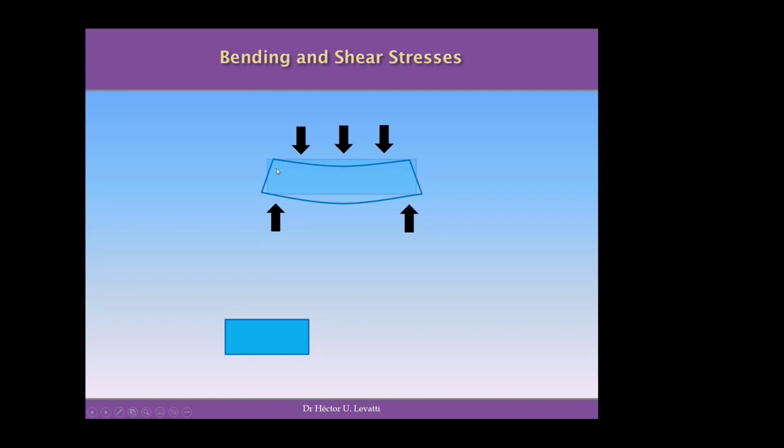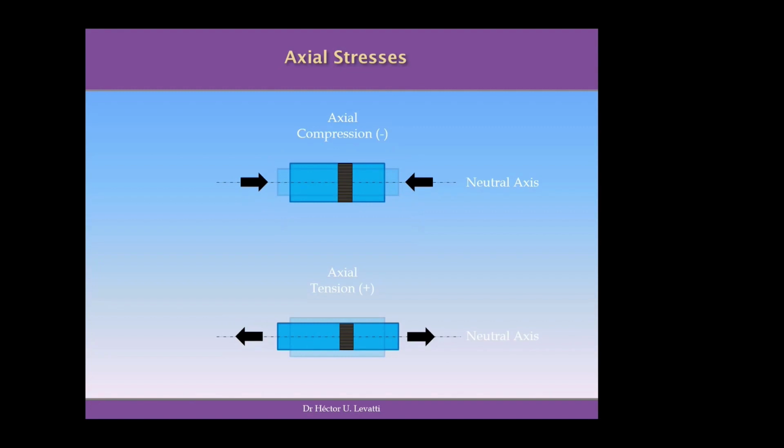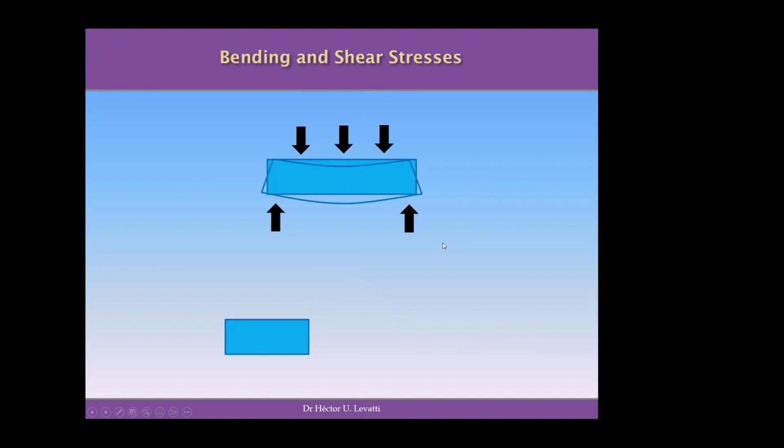So, but there is a particularity in here, because when you bend a beam, you don't have this configuration anymore as in an axial stress. So you are not deforming the beam in this way anymore. You are not shortening the beam uniformly, or extending the beam uniformly. But what you are doing is bending the beam, producing rotations in the cross sections. So these cross sections at the extreme are the cross sections that rotate the most.